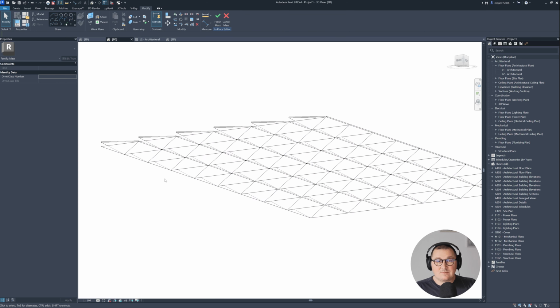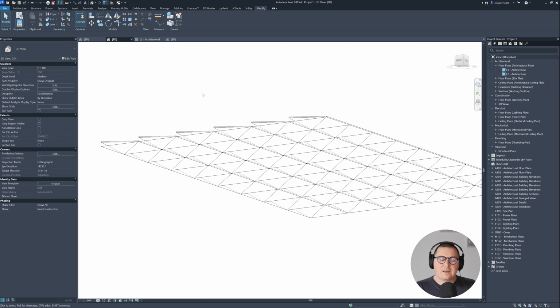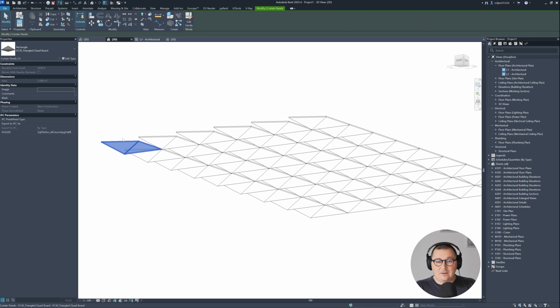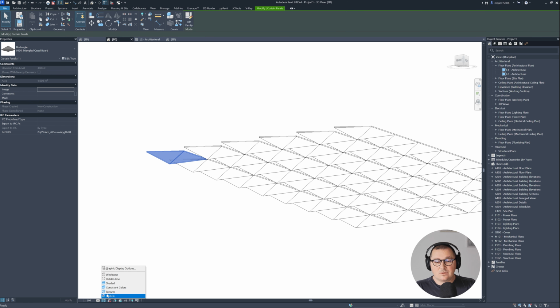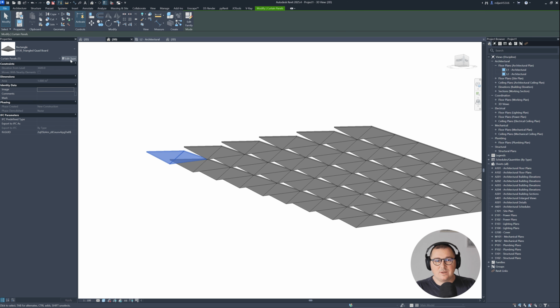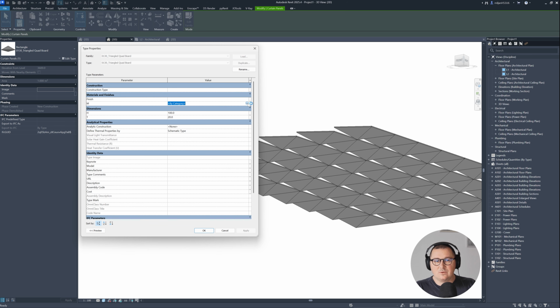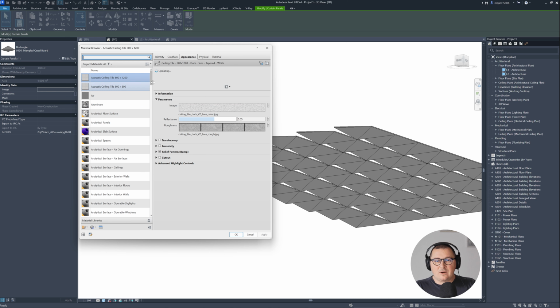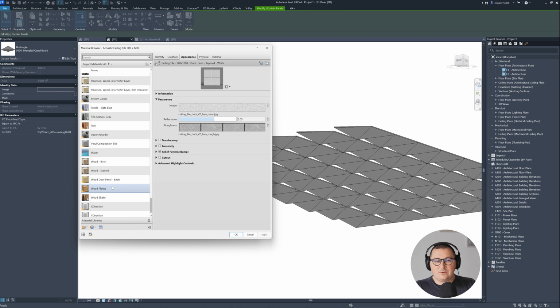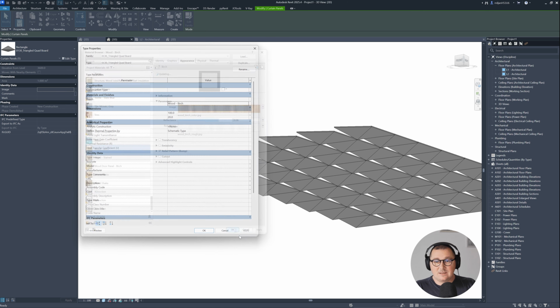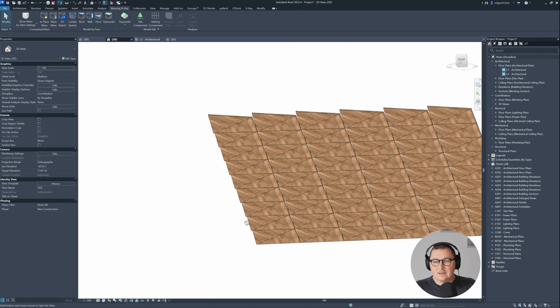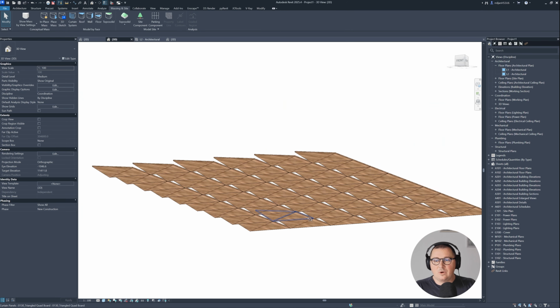There's a difference, but what is very important is to understand how you can create it and what you can do with this. This is a pretty powerful tool, really, in Revit. And by the way, I don't want to forget that we can also assign a material here because we added this one. If I go here to material, to open our family, we are able to add, it doesn't matter, let's say, this wood, and it will be applied to all those components.